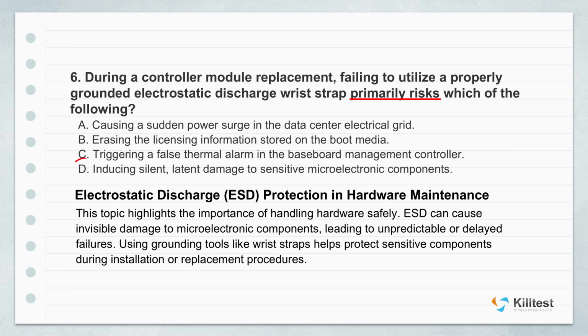But you're not. That microscopic spark carried hundreds of volts. It literally blasted a microscopic crater into the silicon pathways of a transistor gate. Weeks or months later, as the server heats up and cools down, that weakened pathway finally snaps. Suddenly, the server experiences random kernel panics that are completely impossible to diagnose because the hardware passes all normal health checks. It's a tiny, invisible time bomb.